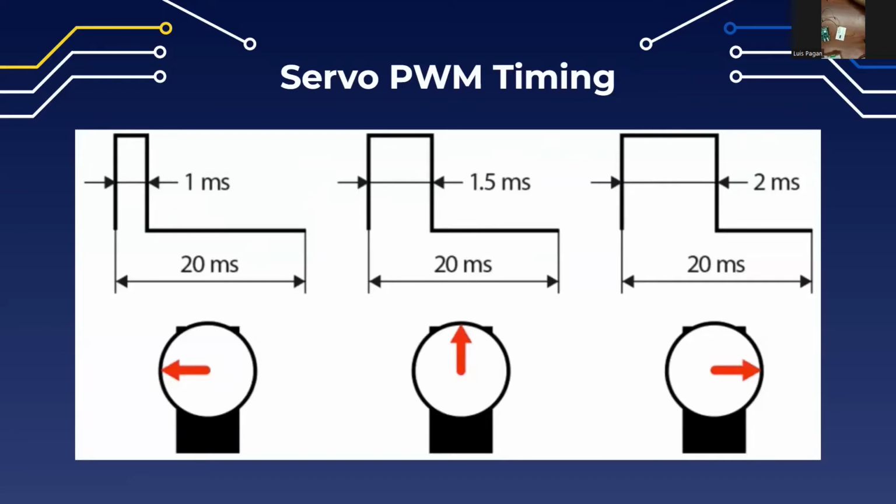Now, when we're using the servo, we want to make sure we get the upper and lower limit of the duty cycle. In the case of these micro servo 9 gram SG90s, I found through testing that the range is between, I think, 2.5 and 12.5 duty cycle.